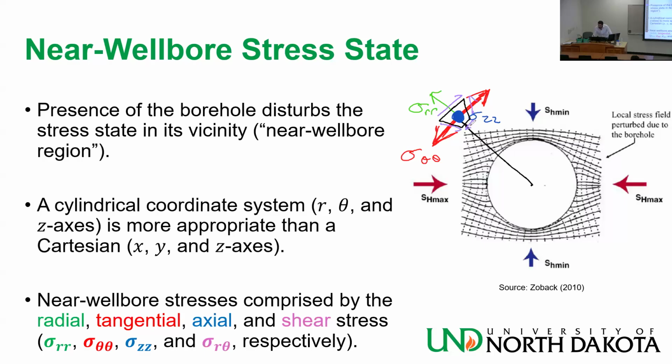Remember, the arrows mean one edge and another edge. They are always sort of like maybe up here and maybe down here. And there is another issue here. The way I drew those stresses, they show the positive direction, the compressive direction, sorry, the positive direction for solid mechanics, which is the compressive direction.